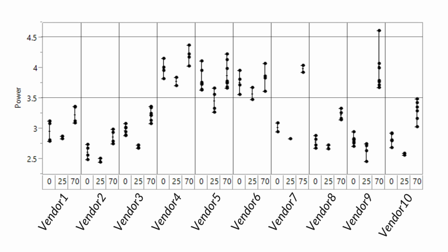It's common to present only the maximum power of a pluggable optic, like 3.5 or 4.5 watts for this QSFP28 LR4. But we observe a lot of differences in the performance and power usage of optics of different brands, and even between different models and generations of the same brand. Note that temperature is also a key factor, and it does not impact all models in a similar manner. One last word on the optics before we move to the next component in a board.